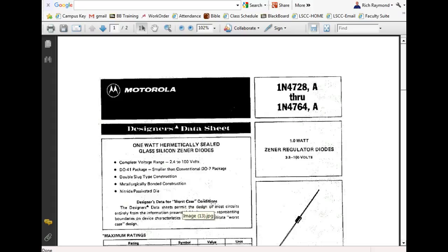We're going to burn that sucker up. So what does that mean? That means we cannot use a 1N4748. We would have to find probably a 4 watt Zener. Wouldn't use a 2 either, right? You understand that? Probably won't be able to buy a 3. I've never heard of a 3 watt Zener, but I'm sure there's a 5 watt Zener. So you'd have to go up.